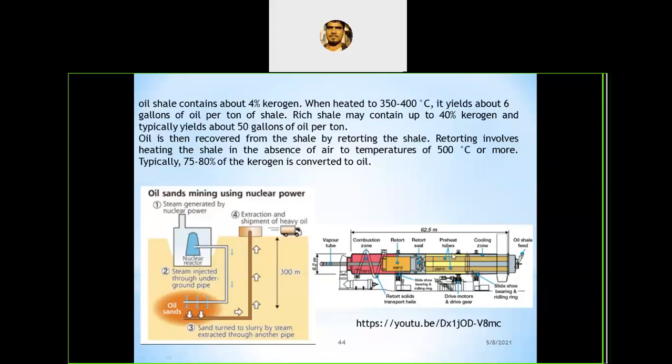Next, once the top layer is separated, it moves into the next section. In that we add some naphtha. The naphtha and this mixture move into the centrifugal chamber, where the centrifugal action takes place. Because of that centrifugal action, it will separate the water particles, the fine particles, the bitumen, as well as the naphtha. Again naphtha is recovered and recycled for the next cycle.